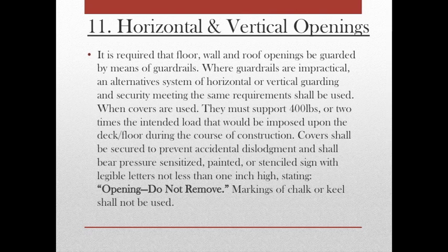Horizontal and vertical openings. It is required that floor, wall, and roof openings be guarded by means of guardrails. Where guardrails are impractical, an alternative system of horizontal and vertical guarding and security meeting the same requirement shall be used. When covers are used, they must support 400 pounds or 2 times the intended load that would be imposed upon the deck floor during the course of construction.